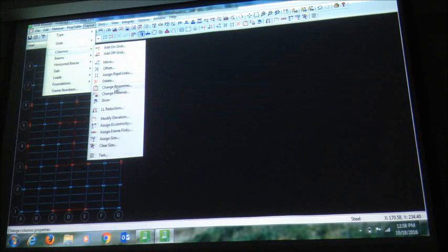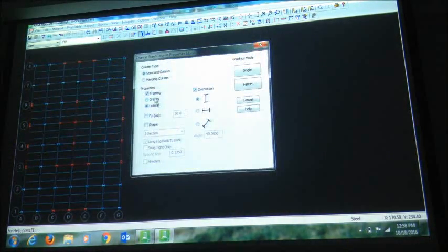Anyway. Any questions so far? Yes, can you show how you made the columns ready again? What was that part? Either you click on this one or go to layout, columns, change properties, got it. And instead of gravity, click on the framing. Instead of gravity, make them lateral. Got it, and then select.